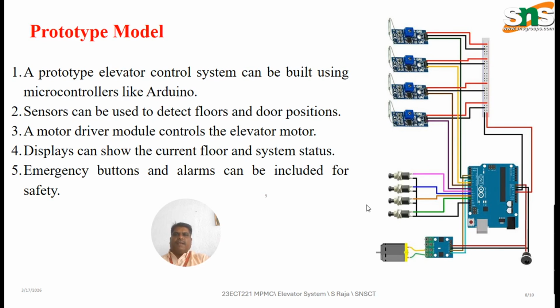A prototype elevator control system can be built using microcontrollers like Arduino. Sensors can be used to detect floors and door positions. A motor drive module controls the elevator motor. Displays can show the current floor and the system status. Emergency buttons and alarms can be included for safety.